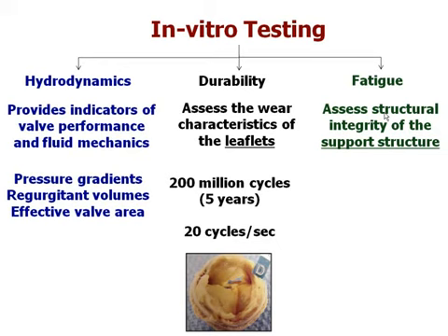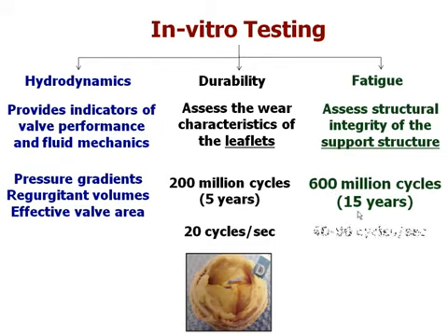With respect to fatigue testing, this assesses the structural integrity of the support structure. And this is run at 600 million cycles, which represents 15 years. And the tester is run at 40 to 80 cycles per second.